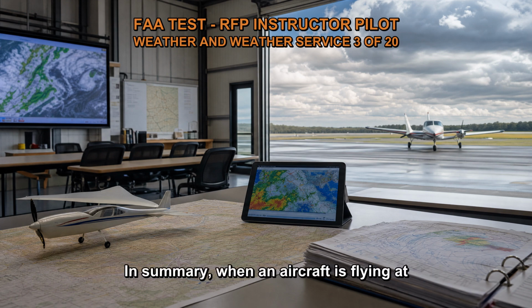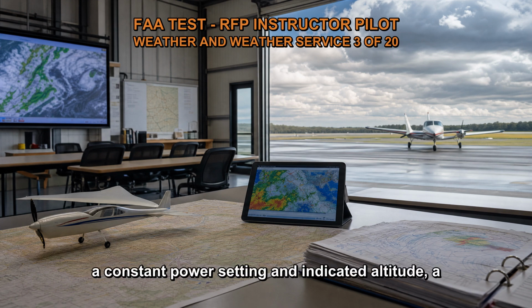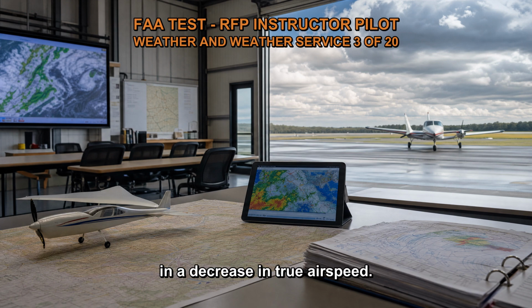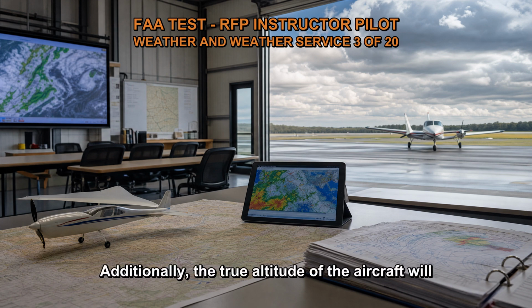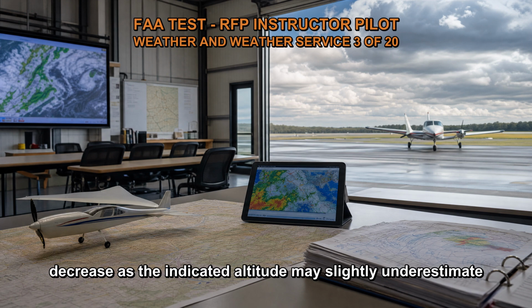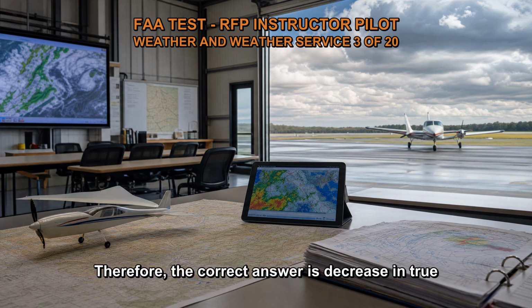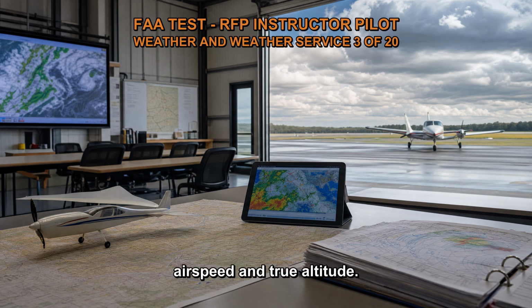In summary, when an aircraft is flying at a constant power setting and indicated altitude, a decrease in outside air temperature, OAT, will result in a decrease in true airspeed. This occurs due to the increase in air density associated with lower temperatures. Additionally, the true altitude of the aircraft will decrease as the indicated altitude may slightly underestimate the actual height above sea level. Therefore, the correct answer is decrease in true airspeed and true altitude.